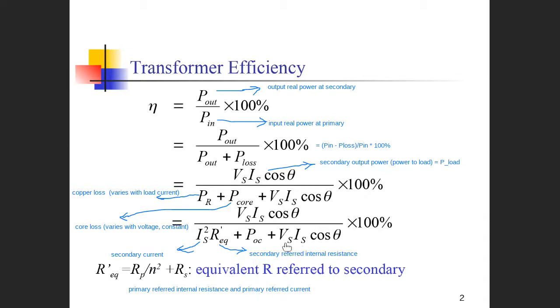And here is the secondary referred voltage, secondary referred current, and the power factor, that is, the loading power factor. The secondary loading power factor and the primary loading power factor are slightly different, but there is no big difference for our practice. You can also use the primary referred voltage and primary referred current. That's very similar, because when you do the calculation you use the transformation ratio, so the relationship between the voltage and current is always very similar.